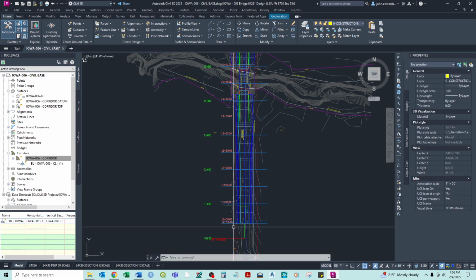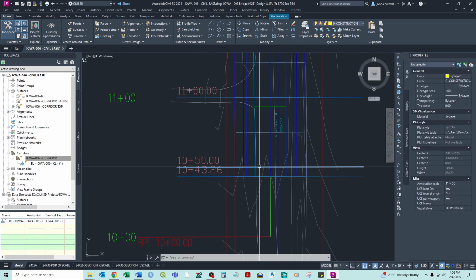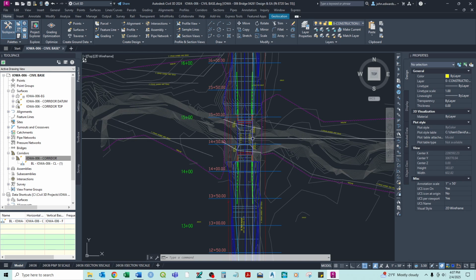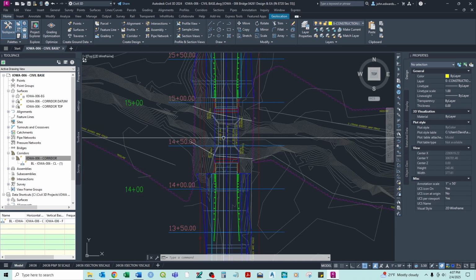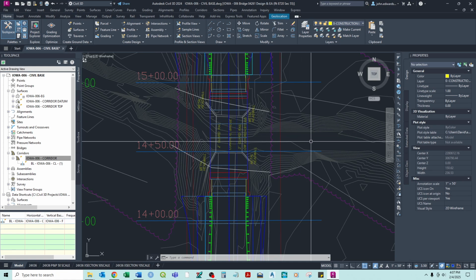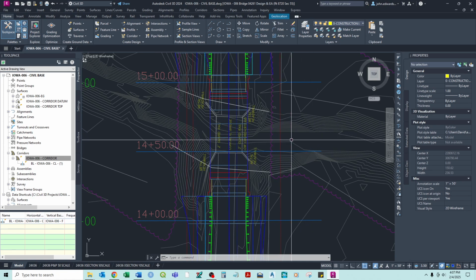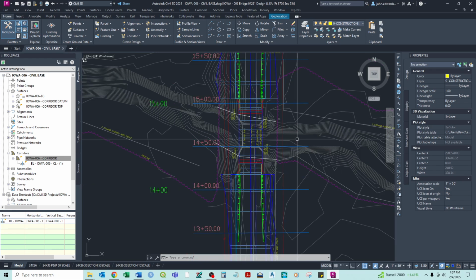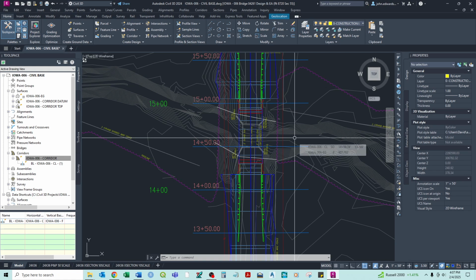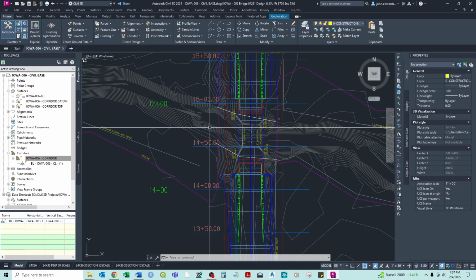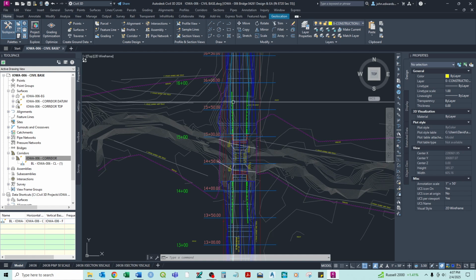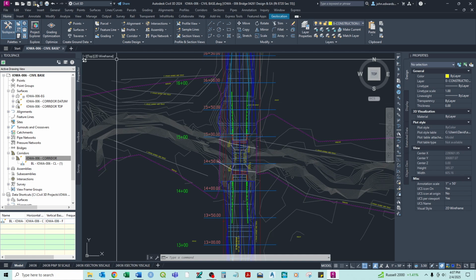We'll right click, and so you see now we've created one right here and right there. Okay, so now we have them every 50 feet all the way down. Like I mentioned before, you could add another one here at your bridge center line, which is probably always a good idea. But sometimes that comes later, and that might be a separate sample line group that you want separate cross-drain sections, completely different from your roadway sections. Okay, but now we have the sample lines,